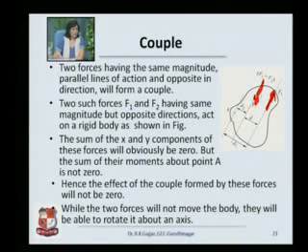The sum of their moments, on the other hand, will not be 0. Why will that be? Because there is a distance apart between these two forces, and if we look at any one of the points, say point A, what will happen is the effect of this force F1 about A. We have studied the concept of moment. F1 into D1 will form the moment M1 about A. Similarly, F2 into D2 will form the moment about A in the opposite direction. The sum total of these two moments is not going to be 0, as against the vertical and horizontal components.